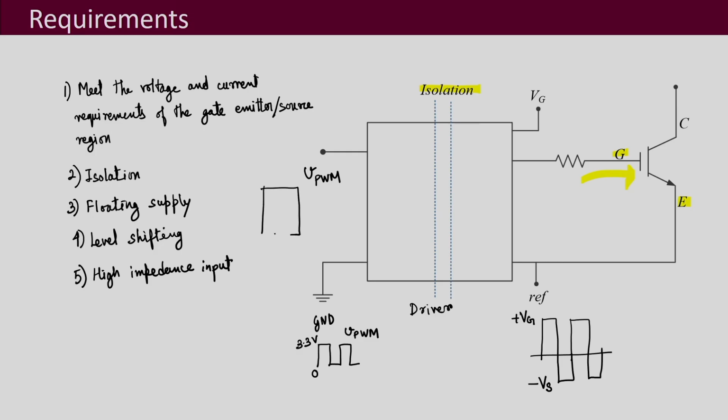Note that this side of the driver is connected to the controller, and this usually does not have a very high current sinking or supply ability. If the driver draws a lot of current or sinks a lot of current, that will load the controller, which is not desirable.